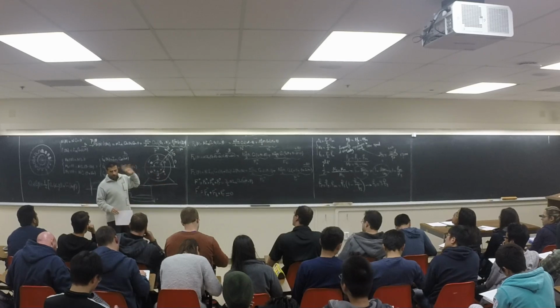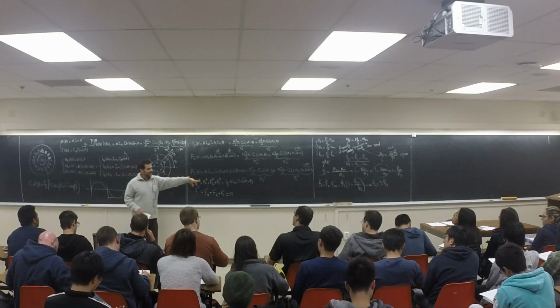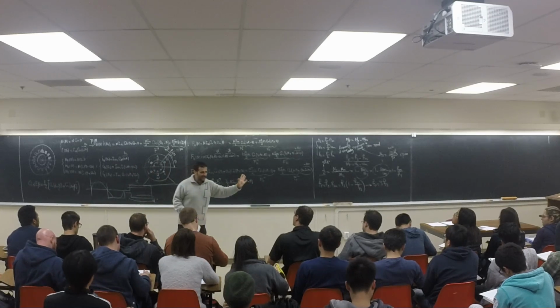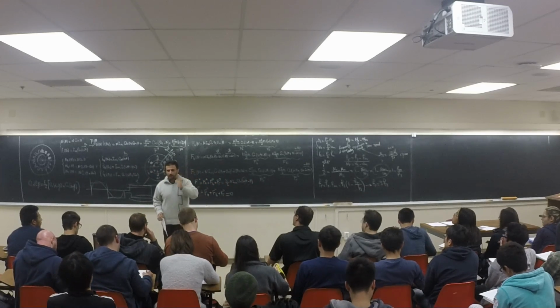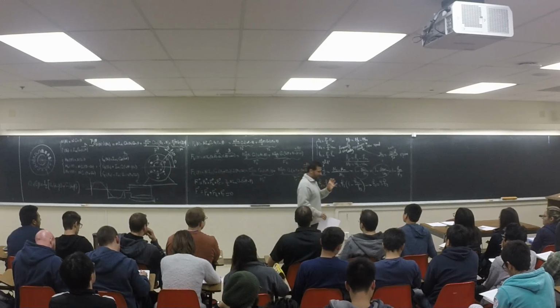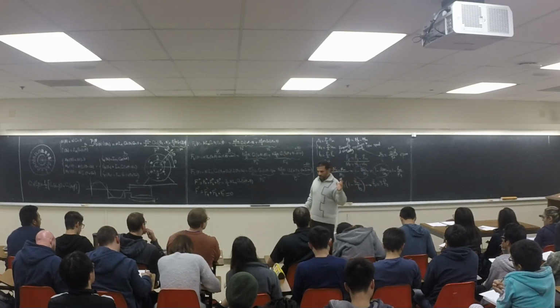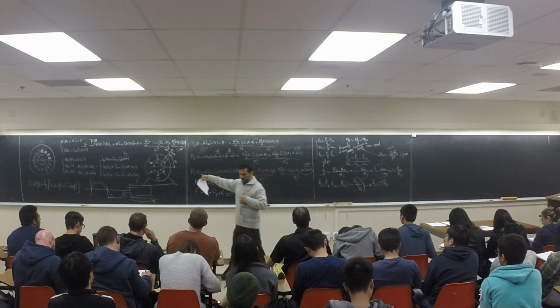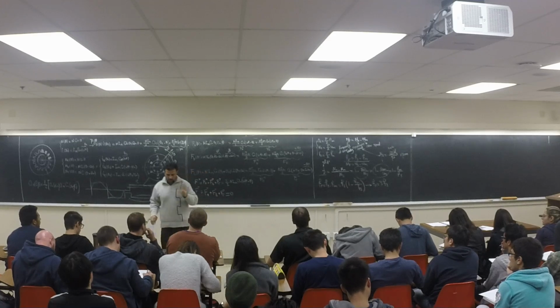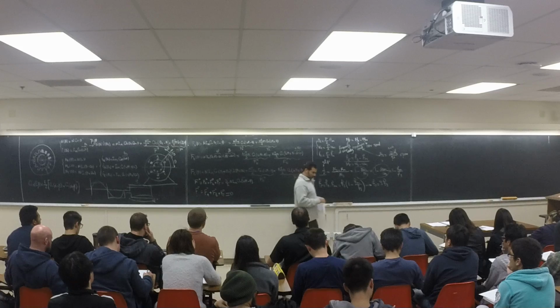Because, as I said, the frequency of the rotor current is almost zero, it is S times Fs. And S is a number usually from 5% to 1% or something like that, a very small number, right? So Fr is almost zero, so there is no core loss in the rotor, right? So that's to clarify the point. Core loss is in the stator, not in the rotor.